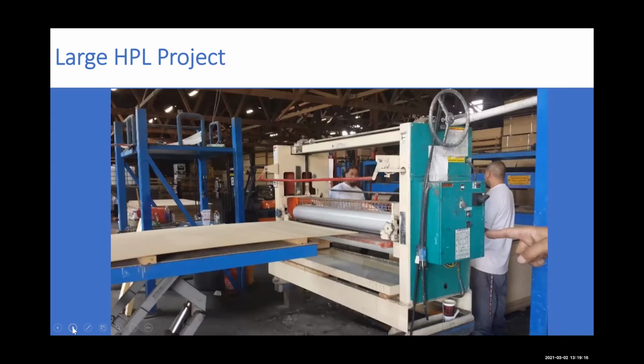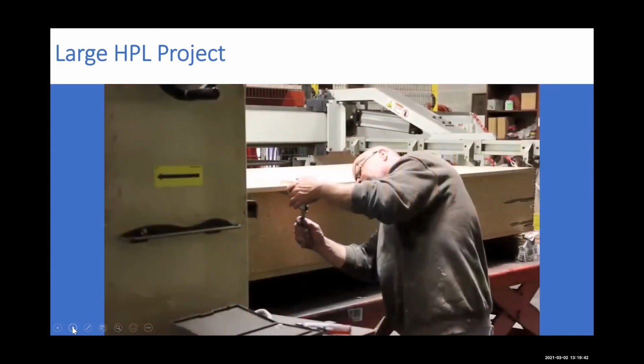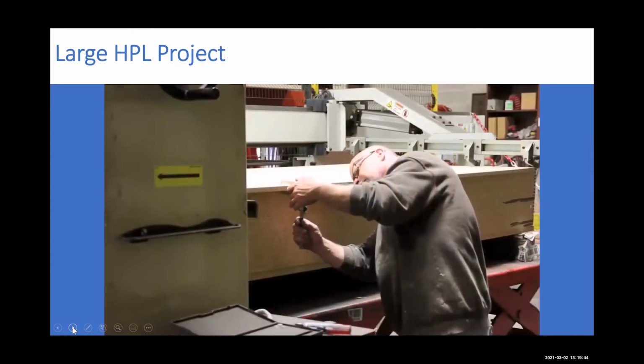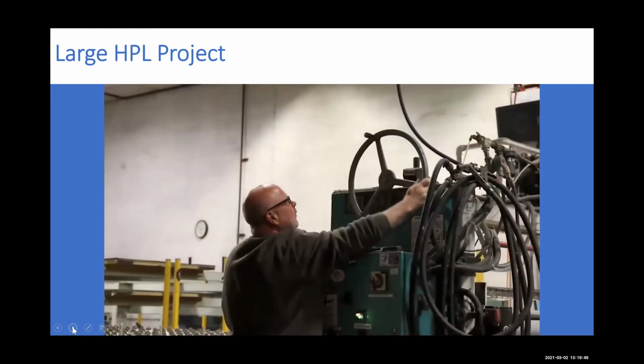Generally, in large-scale production, a glue spreader, such as the one depicted in this image, is used to apply PVA glue to the substrate. Once the laminate is adhered to the substrate, the panels are put in a cold press, like this one, for approximately 24 hours until the glue dries. Now we're going to look at a video depicting a large-scale panel layout process, resulting in a balanced panel.